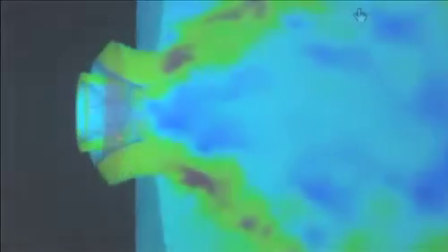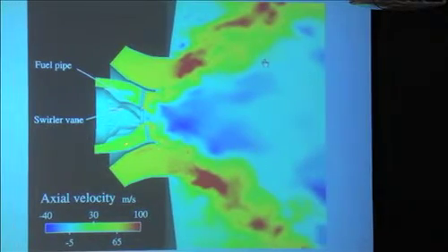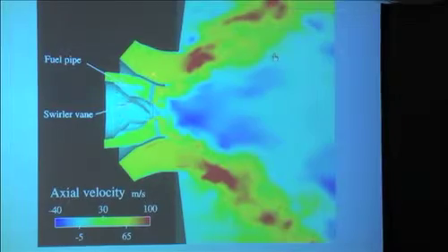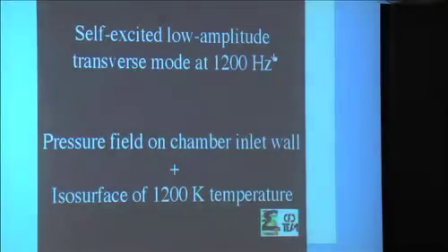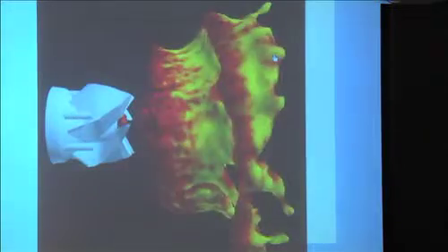So you inject air through the wet zone and through the other one here. So air coming in here and coming in here. All this zone is recirculating here, and the flow actually enters here and just goes both ways because of the very strong swirling motion. A flame in a system like this has very strange behavior. You recognize the shape I have drawn on the board here with a center recirculation zone. Except here, as you will see in a second, this flame is very influenced by acoustics, and I will come to that in a second.